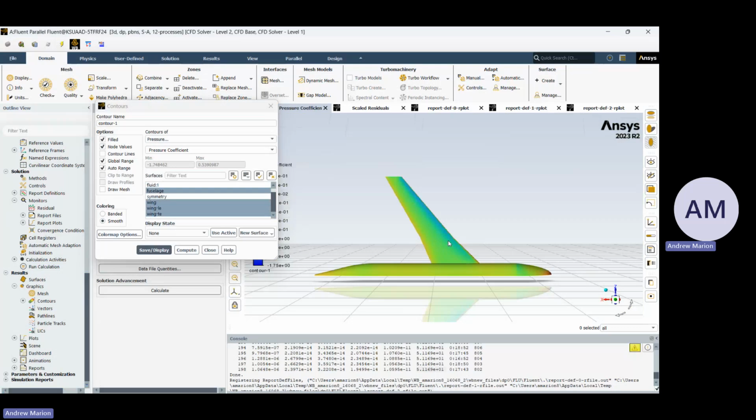So like the lift generation, if you can imagine it as a force going over it. The ellipse typically ends right at the wingtip because that's where the wing ends, and that's where the force is going to end. When it ends right there, that's where the vortices will try to travel and reach to the top. If you can make that dome of force end before the tip of the wing, due to twist, the vortices will not be able to go over to the top because they'll be trying to form underneath the wing, and they'll be blocked.